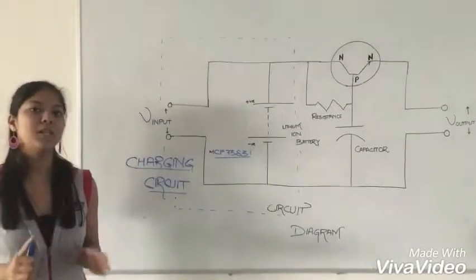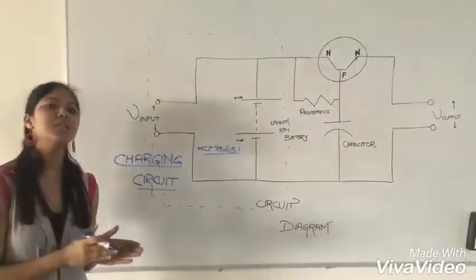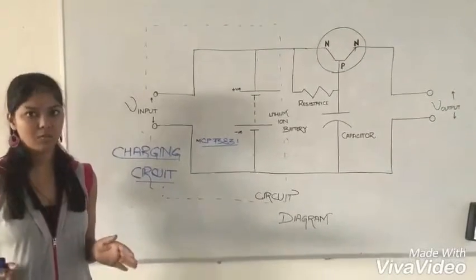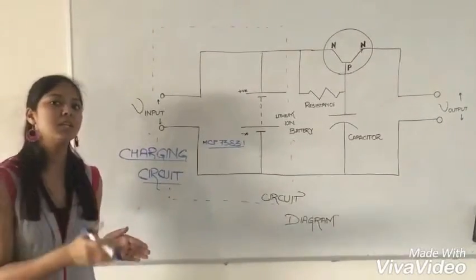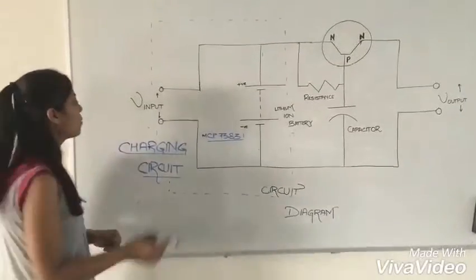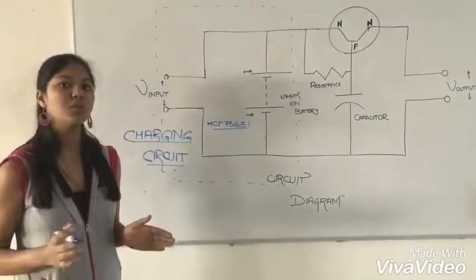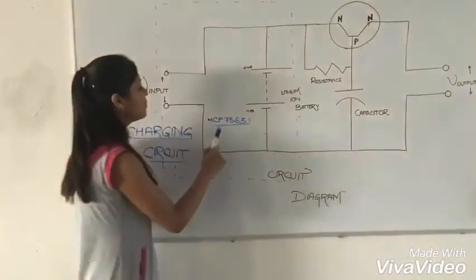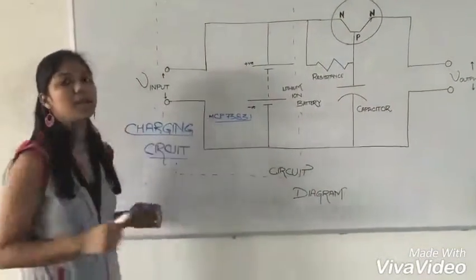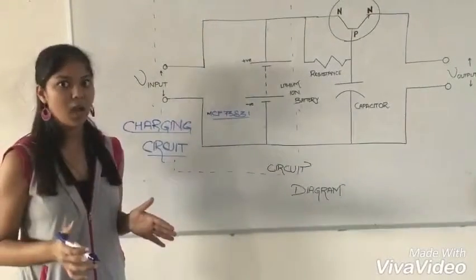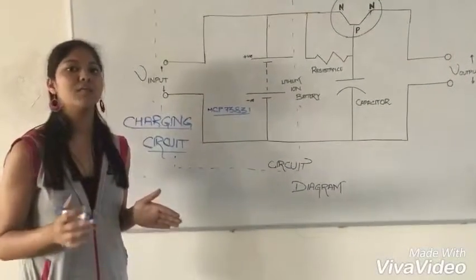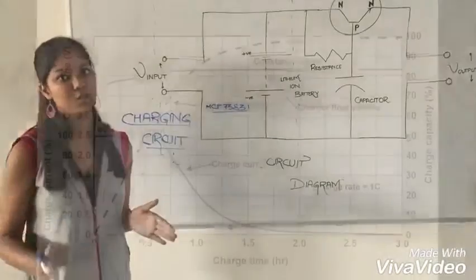A major fact about the lithium-ion battery is that for the first 60 to 70% of its maximum charge, it charges at a constant current. In our circuit, we are providing a constant voltage. Thus, to make the charging process smooth, we use a well-renowned IC, that is MCP73831. It is configured using a constant current and voltage algorithm, and thus we use it for our charge regulation purpose.